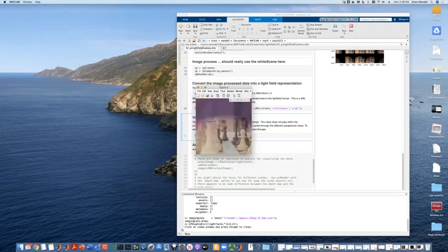Okay, and then all the swirling colors there, that's noise. Basically, those are pixels that don't get enough light, and then the image processor amplifies it, so it looks that way. That's right. And in building a real device, you need to remove the noise and interpolate or something. You need to deal with that issue. The light underneath the micro lens has some shading artifacts, and that can lead to color problems and so forth. You need to think about that if you're building a real device. But this simulation gives you all the different pieces.